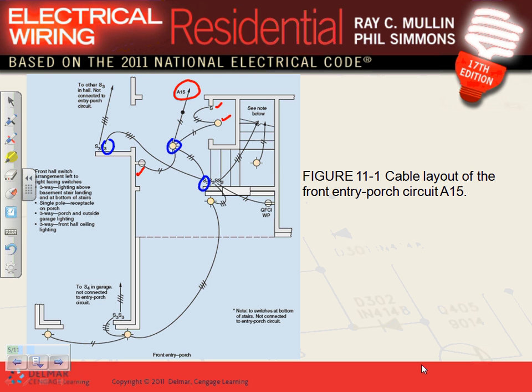And then they stole the power and they picked a receptacle from a switch. There is a switch here that switched this receptacle. If you read how they did it, they're in the porch by code, guys. Every porch has to have a receptacle. The receptacle has to be GFCI. Weatherproof GFCI receptacle. So that's what they did, GFCI receptacle, weatherproof.